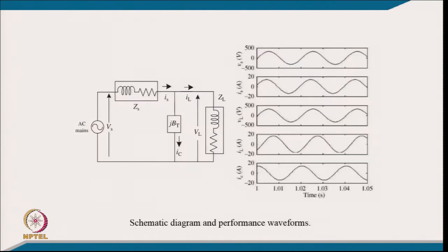I mean, now we can connect this compensator. If you look here, this compensator we are connecting in parallel to the load. Now, compared to the previous problem, where we considered power factor correction, here we are considering voltage regulation. So, now we have to find out the shunt compensator value for voltage regulation. Certainly, its value will be a little larger than for power factor correction. The reason being that we have to take care of the drop of this source impedance also.